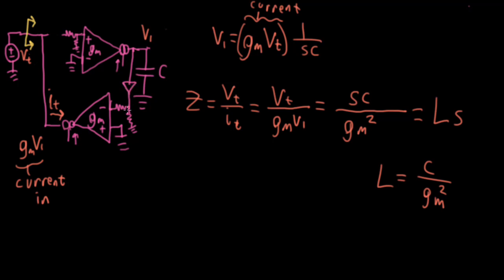So let me put a voltage buffer here, and I'll put a voltage buffer here. That could be an op amp with the output tied to the negative input. And in terms of what you would do with those resistances in the formula over here, you could just fold the effect of the divider ladder here into the transconductance gain. Now we have a voltage controlled inductance.